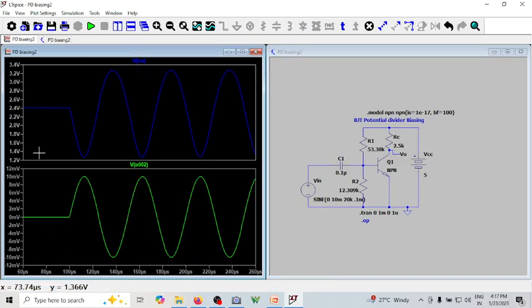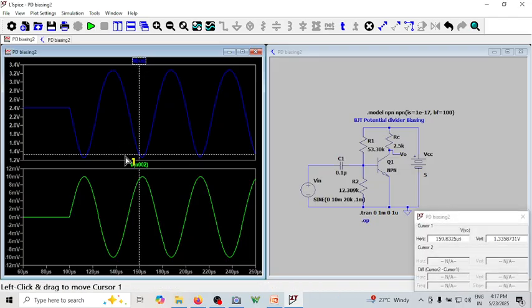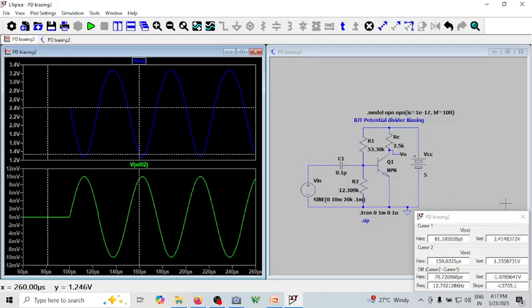See, here I don't have the signal, so the input is 0, but you can see you still have the output. So the output that you have without input is this. How much is that? That is 2.41. So that is the DC voltage at this point without input. Let me write that VC as 2.41 volt. And once you apply the input, which is increasing like this, you can see the output is reducing.